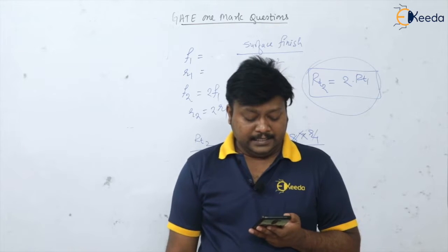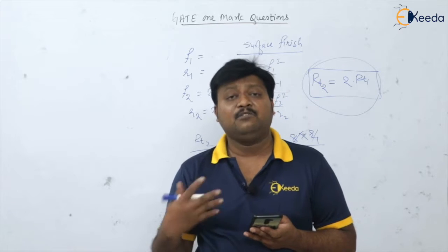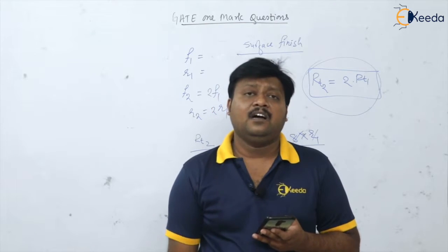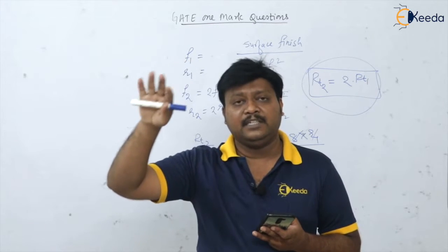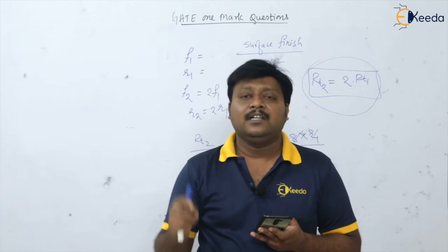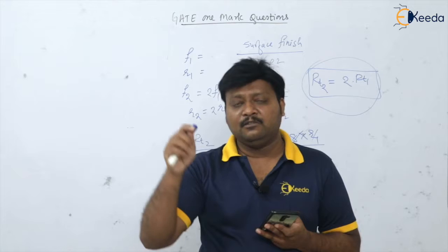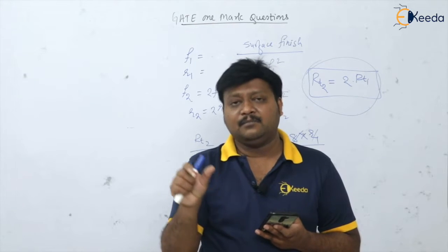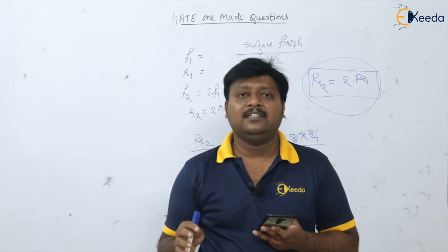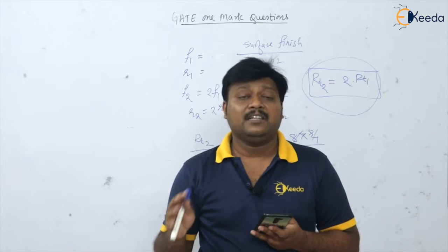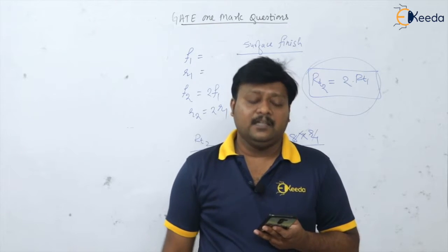Next, crater wear always starts at some distance from the tip because, as we have discussed in detail, the chip is lifted upwards by the tip of the tool and after self weight or gravity it falls down. Till that time the feed is given to the workpiece, so it will always strike at some distance from the tip of the tool, where because of higher friction the temperature rises more at that particular portion and we get this crater wear, isn't it?